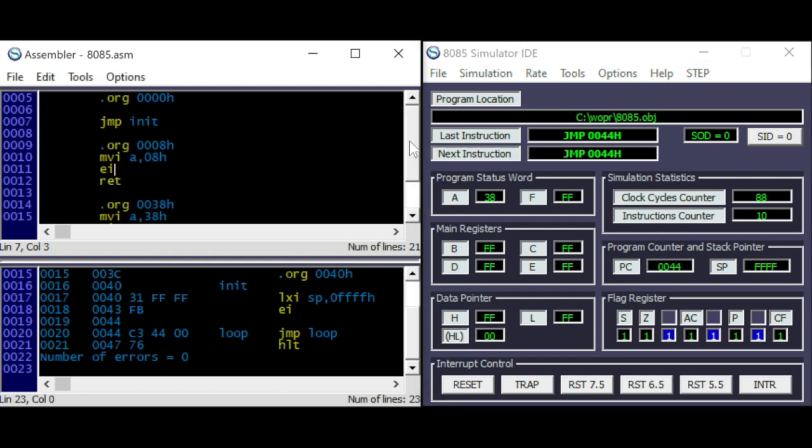The problem you will encounter here is that if you want to change your own interrupt routine, and this is programmed in the ROM or PROM, you can't change it. That's why you will normally have here a jump to a memory address, and then from the memory address you will jump back to either a ROM routine or your own routine. There are several ways to do it. I will show you 2 today. Let's start with the first one.